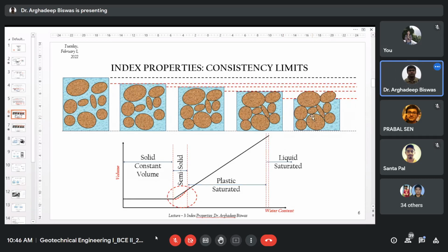This change means the particle shapes, or this arrangement, is somewhat distorted. But the soil remains saturated with its existing or modified void spaces. The amount of water that you have extracted will not be the same as the amount of void space, the amount of total volume reduced. It is a total volume now, which is up to that point approximately, but the amount of water is this much. So here the linear relationship will not exist, but there will be some non-linear relationship.